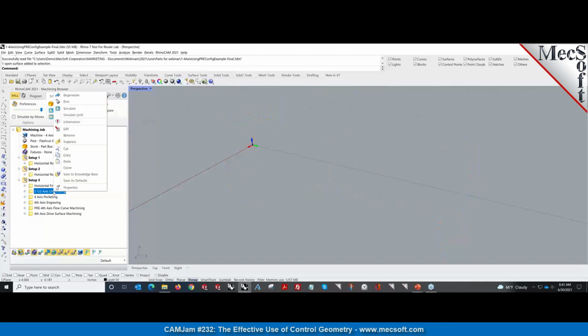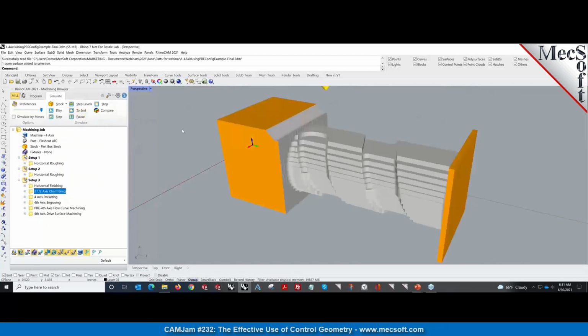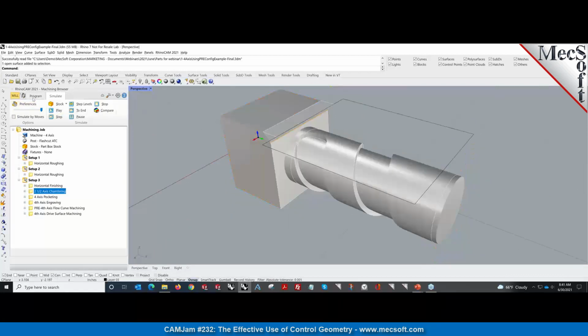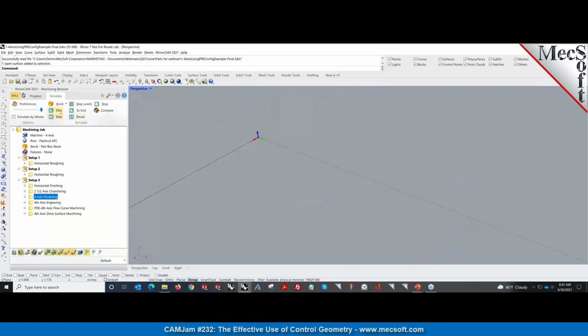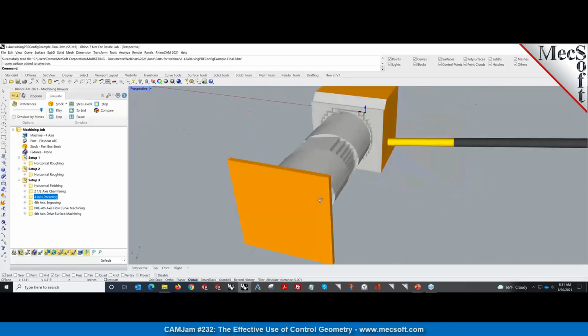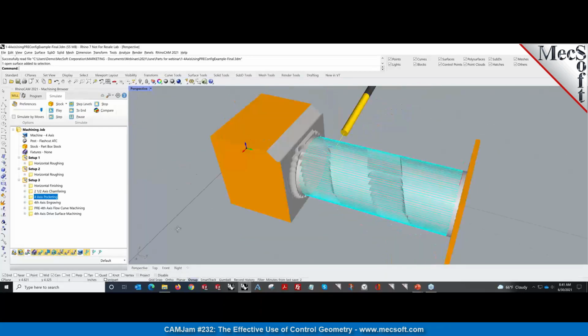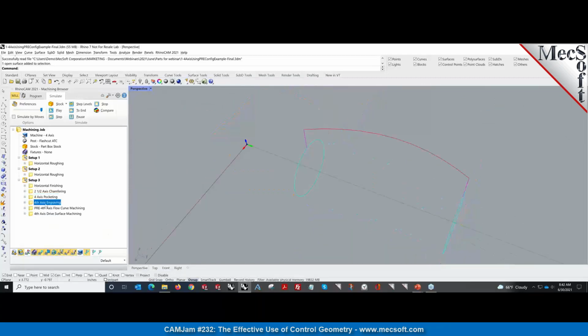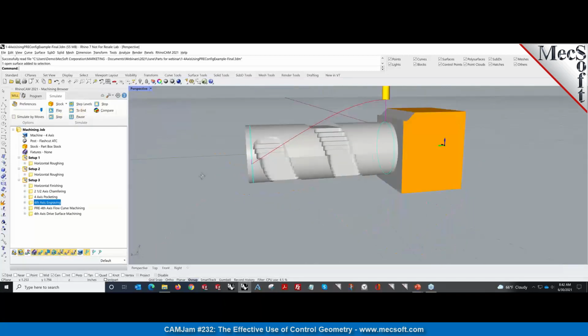And then we did a chamfer operation to remove that chamfer. So all of this is 3-axis methods. Until here, we have 3-axis methods. Now when we get to the rotary part, we're jumping into some 4-axis methods as well. So we're using quite a bit of a combination with 4-axis. We just clean that up. Let me show you the toolpath. So we use the 4-axis face-off operation, if you will. And then we also use a 4-axis engraving operation to clean up the sides to get it like that.